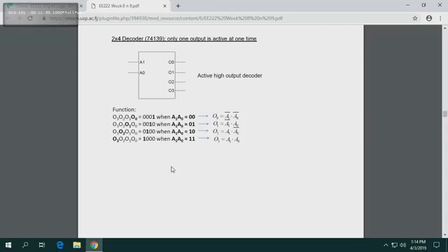So guys, tell me, this is a block diagram. What's sitting inside there? There's actually 4 outputs. So let's talk about our truth table. The moment you see the block diagram, you start to think about your truth table. Once you get your truth table, you can get your equations, either by doing some Boolean algebra, sum of products, product of sums, sum of minterms, product of maxterms, Karnaugh maps, so many methods you've learned.